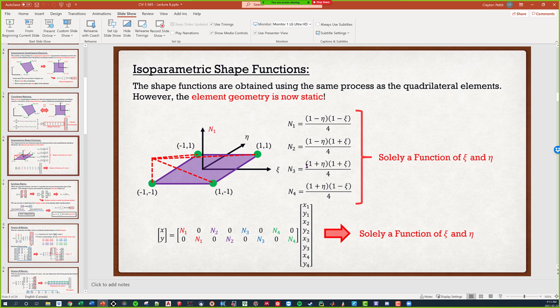Then I go down to my elements, and I create another matrix, and I say I have element 1, and it goes from node 1, 2, 3, and 4. Then with nodes 1, 2, 3, and 4, I can reference my other matrix to find the locations, and then I can find my stiffness matrix. After we code this for one element, it's very easy to see how we can obtain the global stiffness quite simply,